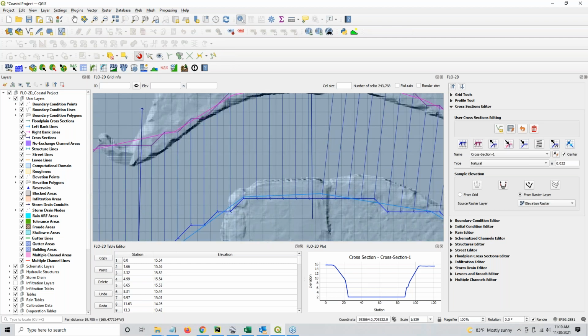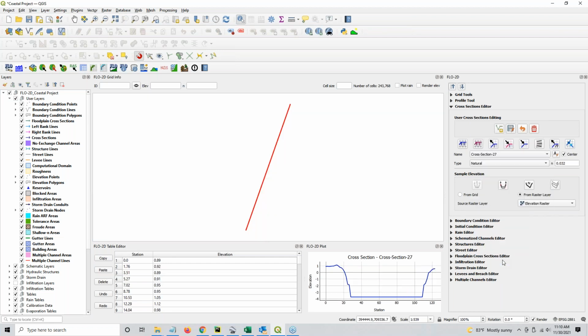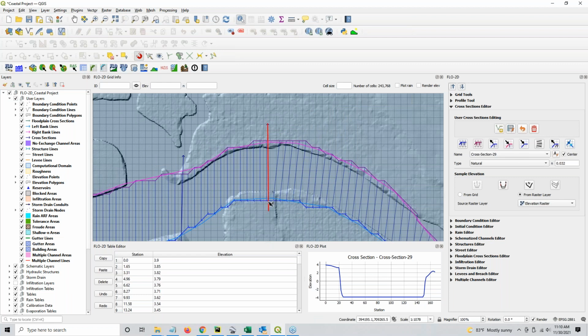So remember, when I snapped that data off that cross section, let me get down here to one of these and see kind of where we are. Let's go down here a little bit further. Yeah, let's get this one right here. So when I draw this cross section and I snapped the elevation for the part of the cross section that was represented by the LiDAR data, it takes the station elevation from right here to right here.